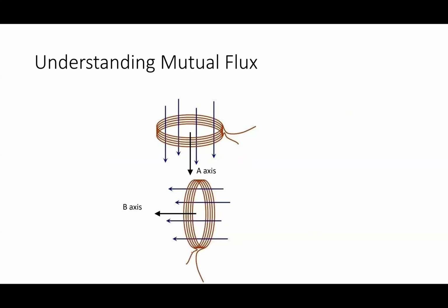All right. What about in this particular picture? What would I say here? Theta R is now basically 90 degrees. So the flux in B from A works out to be N times the area times whatever the B field is times the cosine of 90 degrees. What's that equal to in this particular case? How much flux is linking in through coil B from A?